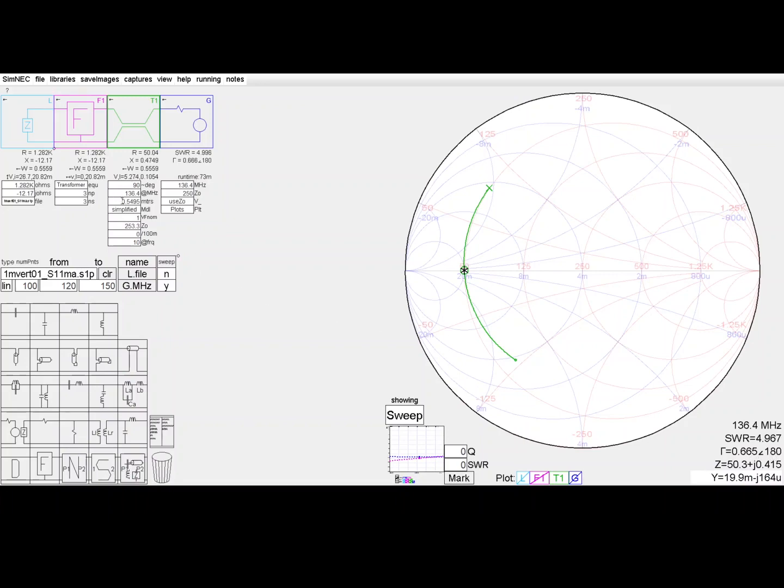If we take the transmission line out, the reflection coefficient of here is 0.674. It's approximately the same, but just about the accuracy of my clicking the asterisk on there, at about 0 degrees. So the chart only works in rotation when the reference impedance matches the transmission line ZO.